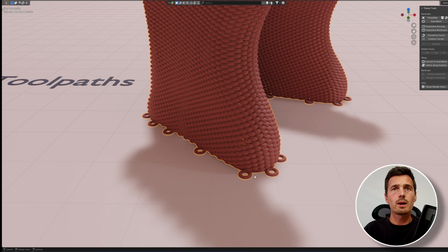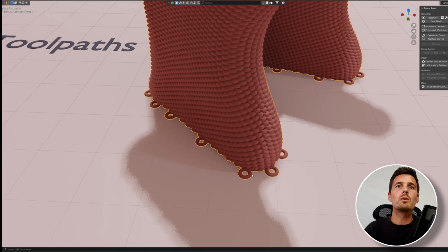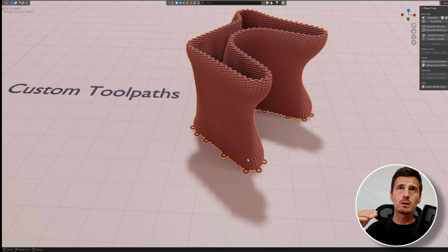And one thing that I forgot to mention is that warping is a big issue. So your object can start to warp just like desktop printing. But if you go towards robotic printing, everything gets bigger. So your mistakes also get bigger. The warping also gets more severe. These rings are, for example, to mechanically fix the first printing layer to the printing bed. Also, it will be flatter than the top part. So take that into account too. So you can do some surface treatment afterwards. That's of course extra costs.